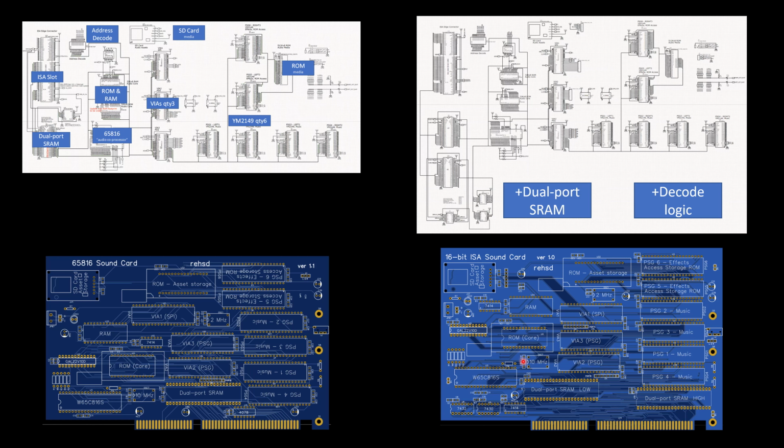This card here, all on its own, could also interface with the keyboard and mouse through SPI, since it has native SPI support through a VIA, because I'm accessing an SD card. So there's a lot on this card. I have a lot of flexibility in what I can do with it, but at the heart of it, I have a processor and its necessary components to make it run. I then have these VIAs that will let me control the sound generators, and those sound generators then create channels of audio that I bring together and send out through this audio jack right here.